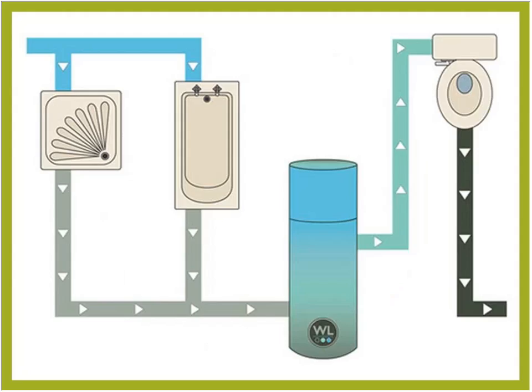So this is just a basic, crude example of a Graywater system, and Graywater is pretty hip, pretty cool. A lot of people approach us and say, oh, we need to do Graywater. That's the cool thing to do to save water. But believe it or not, all those other things we talked about, stopping leaks, getting more water efficient toilets, fixtures, and aerators, those are the types of things you want to do way before you ever consider a Graywater system. Number one, because they're going to save more water, and because they're cheaper, they're lower hanging fruit.